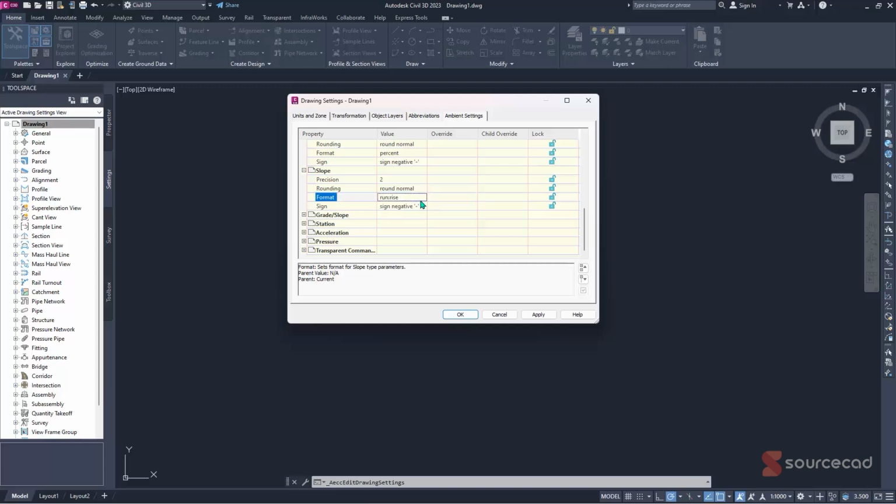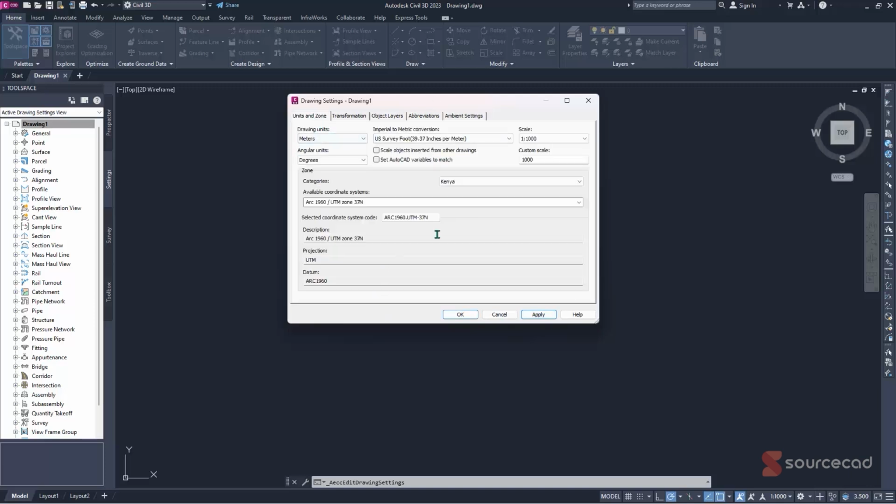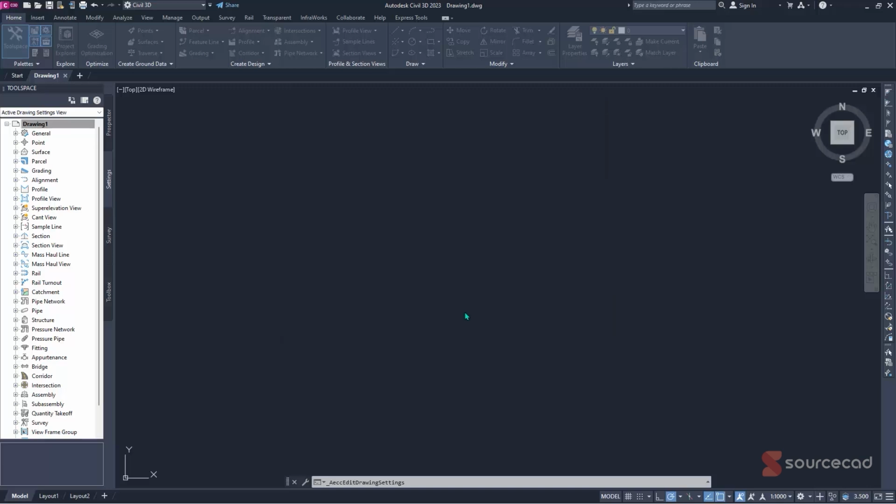So it depends on the team that you're working with, as well as the project deliverables that you currently have. So you can always change these things that you want. So let's say you want to use foot per meter squared, you can always change from here. So once that's done, you're gonna simply just hit on apply, and those changes will be applied in your project. So right now we have the metric just as we set, then hit on OK. So that's the way we do for metric.